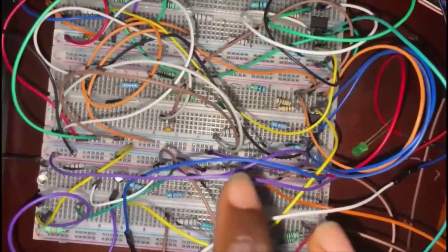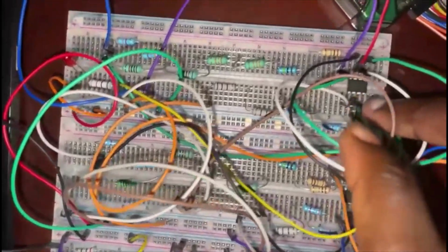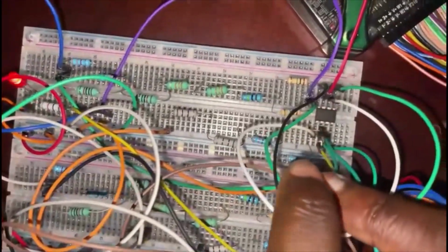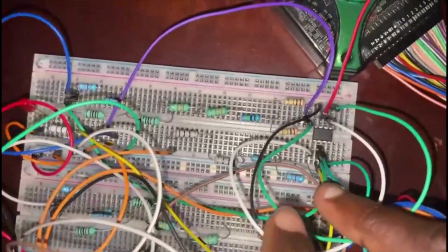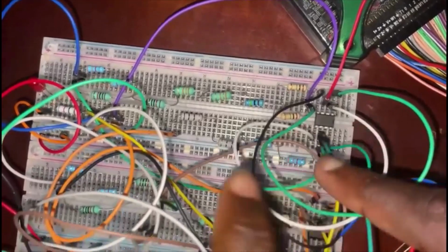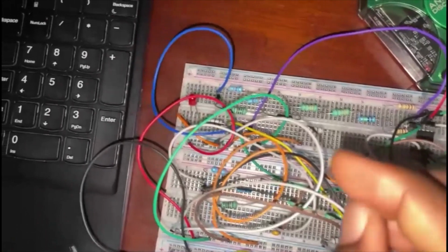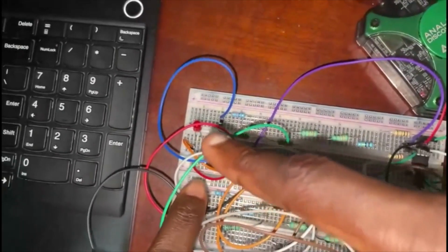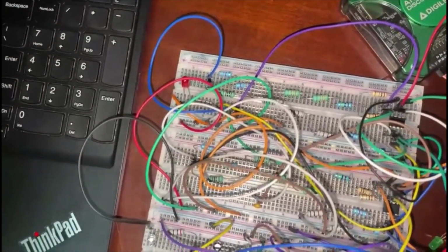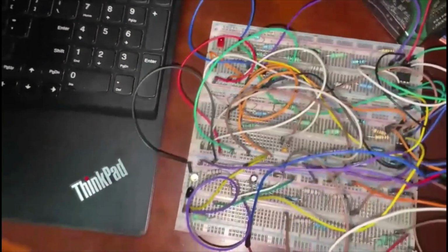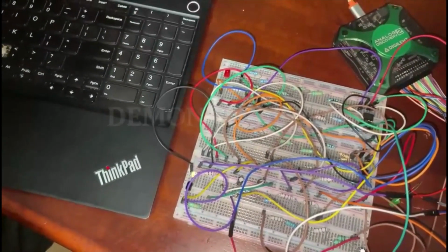Now we need to magnify that small heart pulse we've got here into a bigger one to be able to turn on our LED. So this op-amp again has the same magnification as the one before, and it does another active filtering and then amplification. Now the final process is for that voltage or that input signal to come and be used to power our LEDs, where in the form of which your pulse is moving. Your pulse is moving, yeah. So we would like to demo it for you to see.